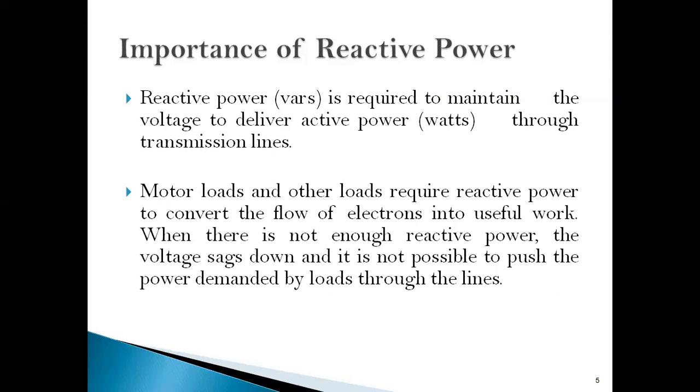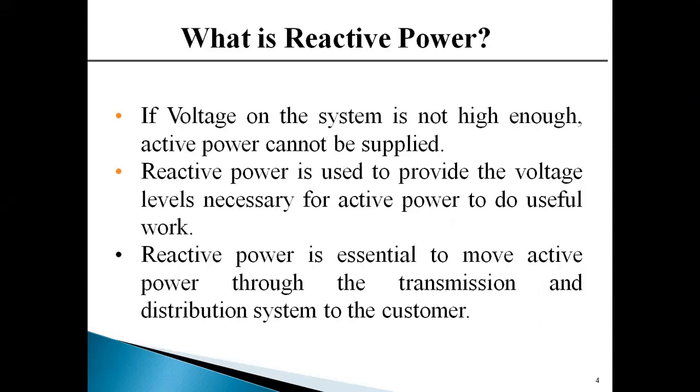For the required power to be transferred over the transmission line, we need proper reactive power to maintain the proper voltage. So this is the significance of reactive power. In this slide, I have given that it is essential to move active power through transmission.